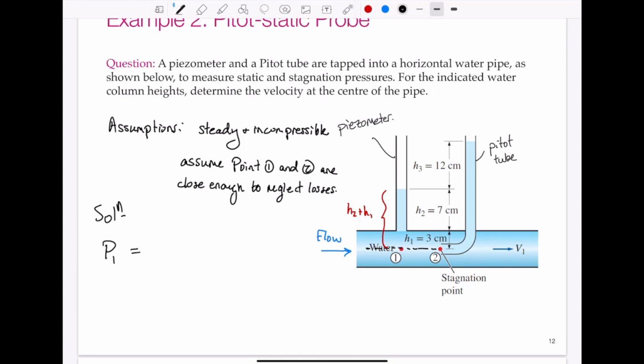You can push really hard at one end, and then some distance later, the static pressure almost goes to zero because there is so much loss in that section of pipe. We'll get to how we deal with that a bit later on, but we don't yet have the tools to handle any sort of losses in our fluid flow using Bernoulli's equation.